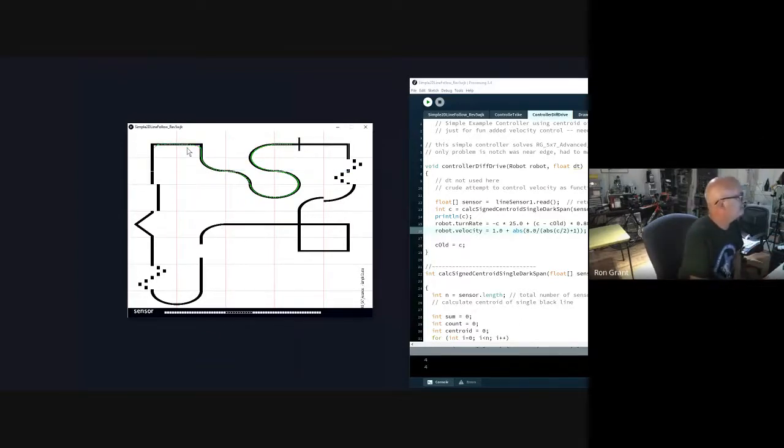But you can see the cookie crumbs as the robot drives. You can see the cookie crumb trail and how well the robot's tracking. And in fact, let me move the sensor back to the center of the robot, because there I noticed, and Will can probably explain some of that fairly well, that the robot becomes very unstable. So here I have a very high gain, and it did go the wrong way on that intersection, so it's retracing.